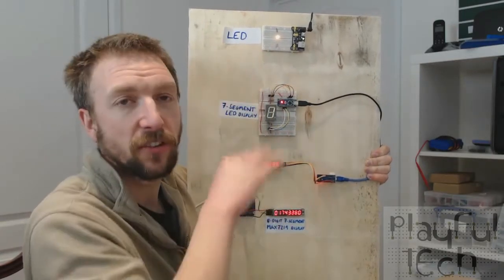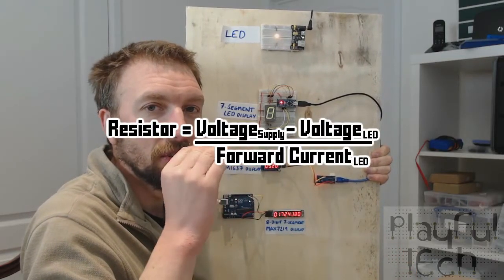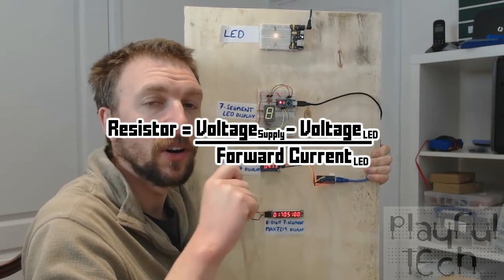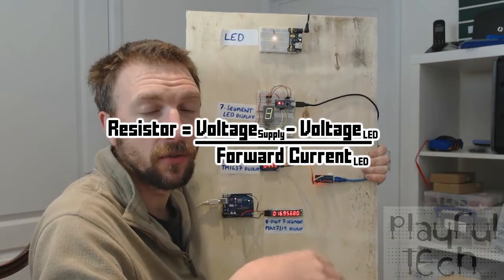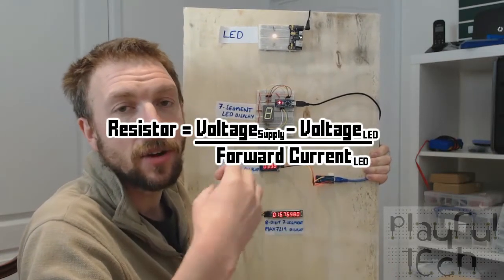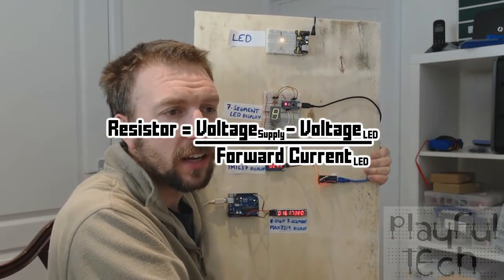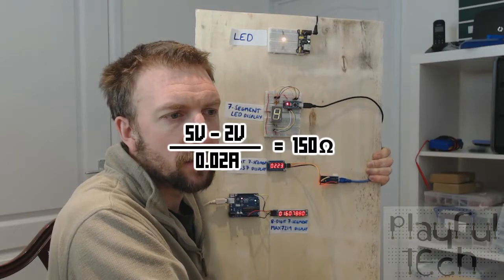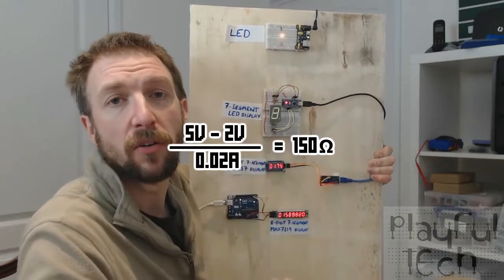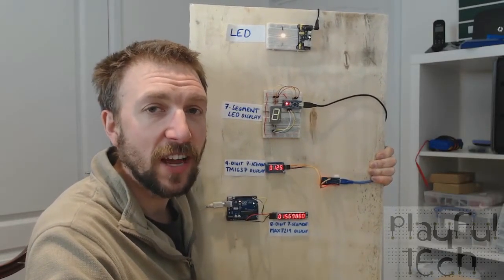Then what you need to know is what's called the forward current across the LED, and for this one, it's about 20 milliamps. So you've got your voltage drop of 3 volts. You divide that by the forward current you want, which is 0.02 amps, and you end up with a value for the resistor. If I plug that into my calculator, 3 volts divided by 0.02 gives me a resistor value of 150 ohms.